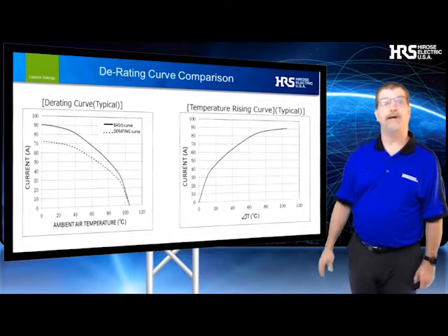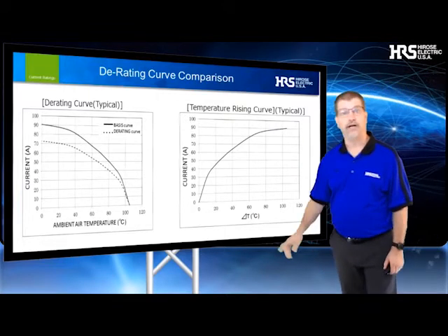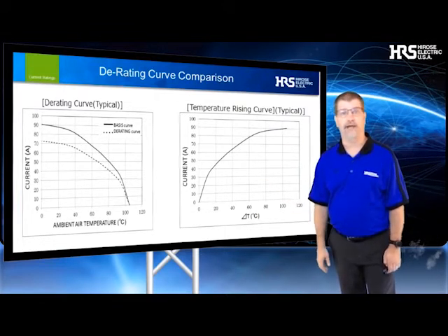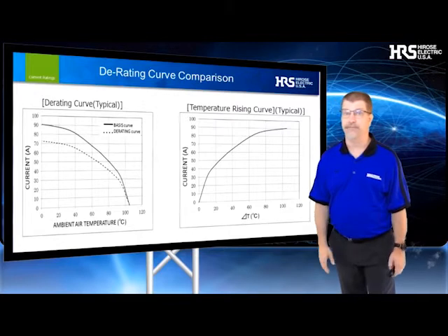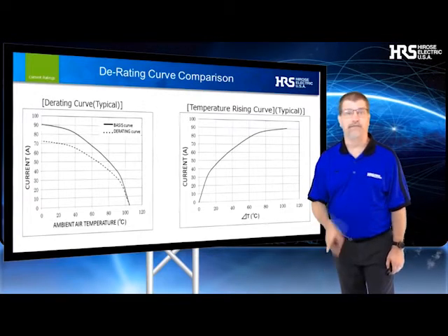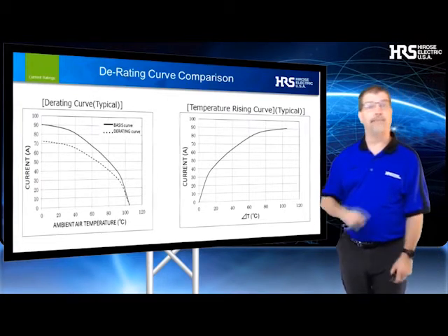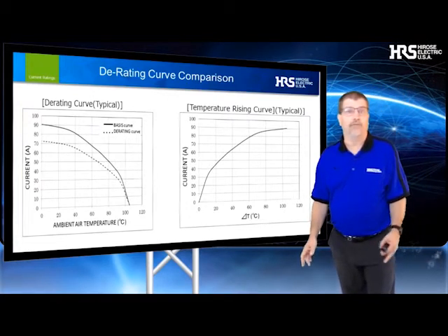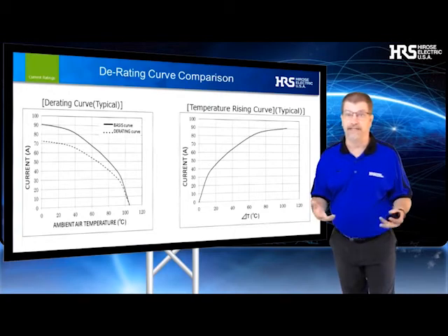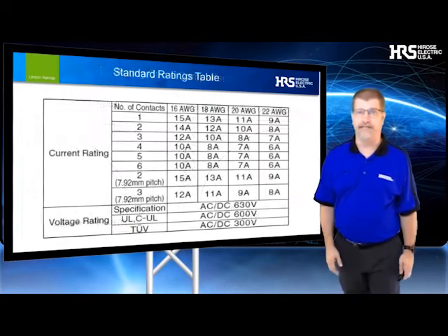Here we see them side by side for the same connector. The dotted line shows a safety derating applied by Hirose of 80% from the initial tested value. For most users, the standard product ratings will be fine. However, your application may push the temperature envelope or even the current rating, and if that's the case, it's always wise to dig a bit deeper.